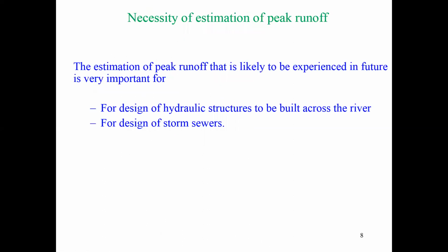Okay. So why are we concerned about the peak runoff, why do we need to know what the peak runoff from a watershed will be? The first reason: if the runoff is very high, obviously it will create a flood, and we don't want that. There are some other reasons also. If we want to prevent the flood and create some hydraulic structures across the river, obviously we need to know the peak runoff, which will be the design runoff. And for carrying the water of this runoff through the storm sewer, we have to design that, so we need a design flow. This peak runoff can be the design flow for that storm sewer. So basically for these reasons, we need to know the peak runoff from a watershed.